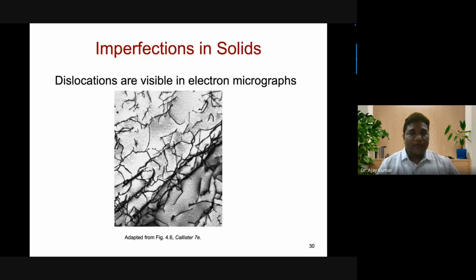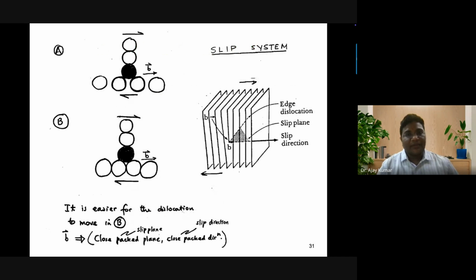So you will be knowing about the different types of crystal structures like FCC, BCC, because each material has particular crystal structures, right? Accordingly, it will behave. So for FCC materials, there is a concept known as slip systems, where we have slip directions and slip planes. And in the close packing plane only, the deformation will happen very easily.